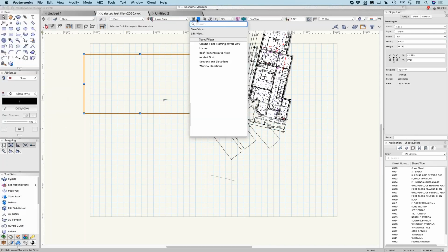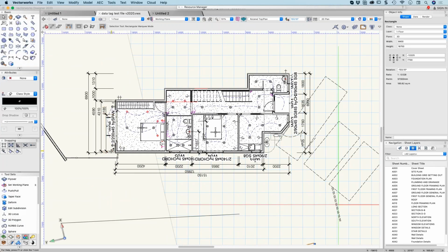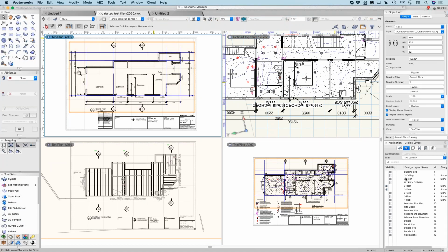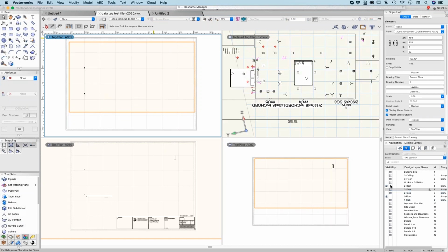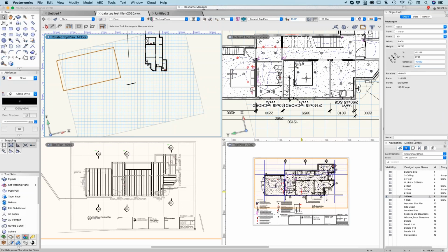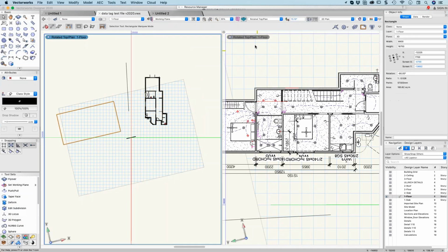And we'll reset our save view. Rotate a grid, and turn on our multiple view panes, which is the letter M, M for Mary. So here we're going to go to a floor plan. So that's floor one, and I'm going to close that one, and split this one.